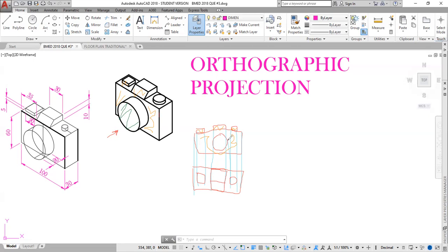We would then have this cylinder which protrudes out. And of course, this will look like a square. So you would not be able to determine that this is cylindrical unless you're viewing it from the front. So in order to see how this really looks, you have to combine at least two views, the front and the plan, to have a true picture of how that looks.